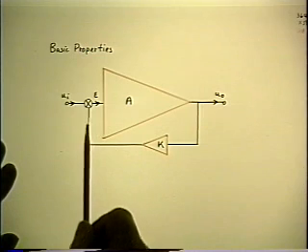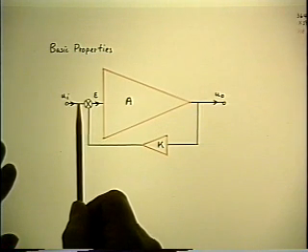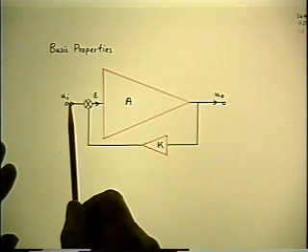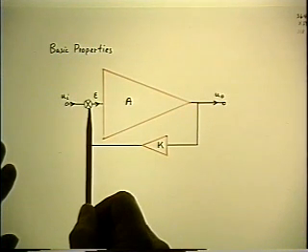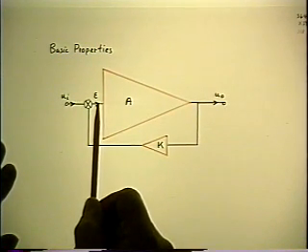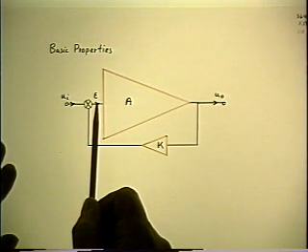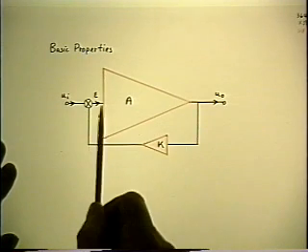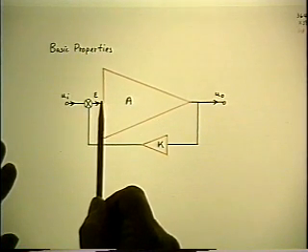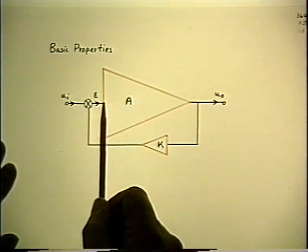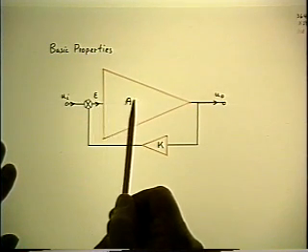You attenuate them, subtract them from the input, but there aren't any distortion frequencies in the input, so when you subtract distortion frequencies, they come through in the error signal with reversed phase. Small, because they're attenuated.